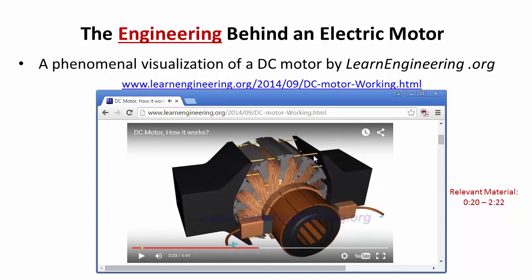Okay, so then this gets more to what a current rotor looks like. Notice that they use a lot of different coils of wires. So the armature consists of a lot of different coils of wires. Each one is connected to a commutator ring right here, and you still have the brushes in there. Then one of the things that they do is they put what they call a ferromagnetic material in between them. So this would be like an iron core, and what that does is it concentrates the magnetic field so that you have essentially more force, so it makes it much more efficient. Okay, so that's how a DC motor works.